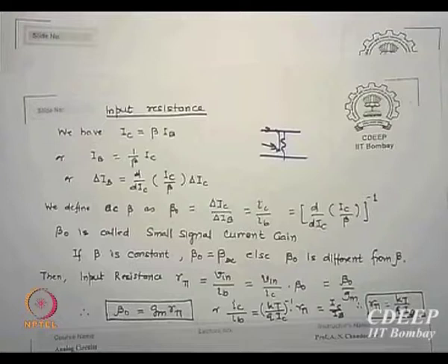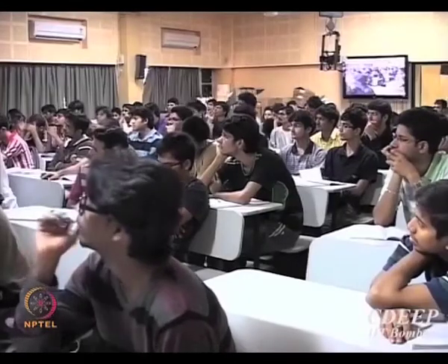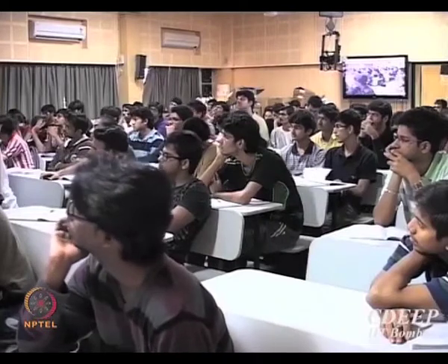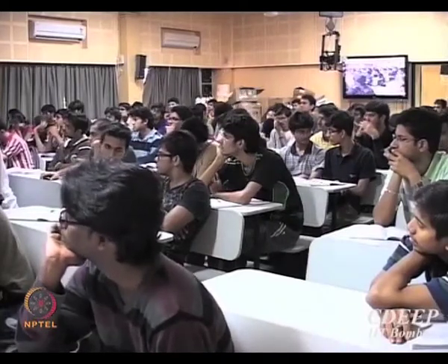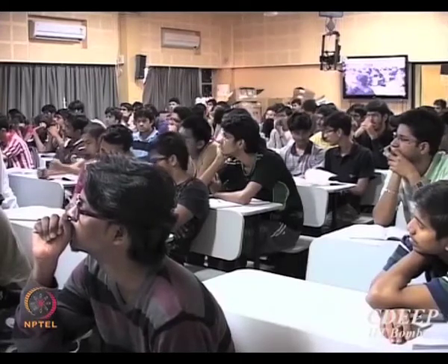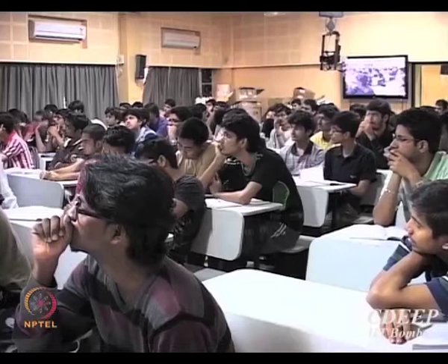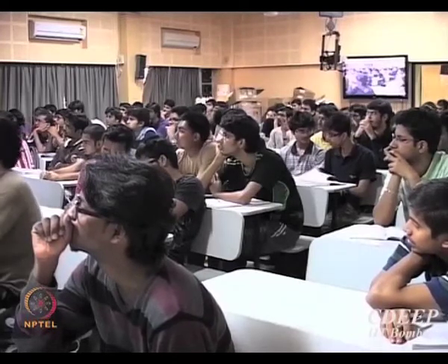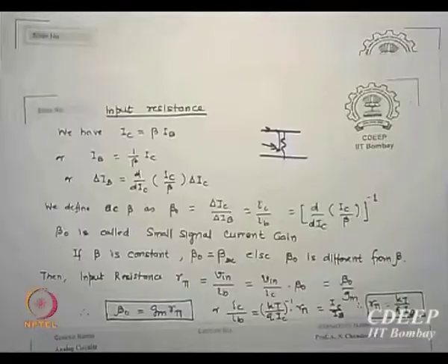So first we must say what is internal to us, and then when we make the equivalent circuit, the transistor will be replaced by all this together, and then externally we will put whatever we actually have in a circuit and solve the whole of it. Is that point clear, why I am doing it? I want to represent this transistor as if it is in circuit form. Otherwise, what model do we keep? I cannot write IC is so much cosec HW by LV plus cot H something. Those equations I cannot write for transistors in a circuit. So I want to put everything in circuit form. So this is also one value which I want to know equivalently. Very good.